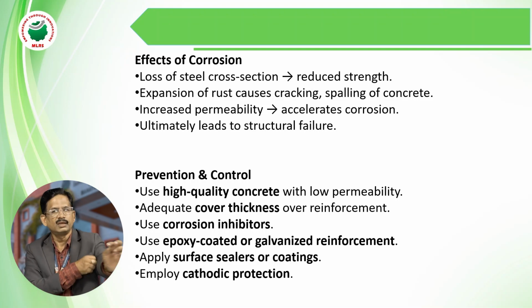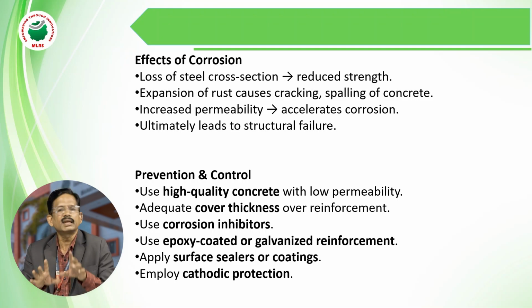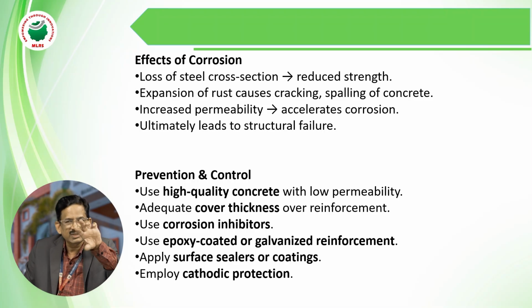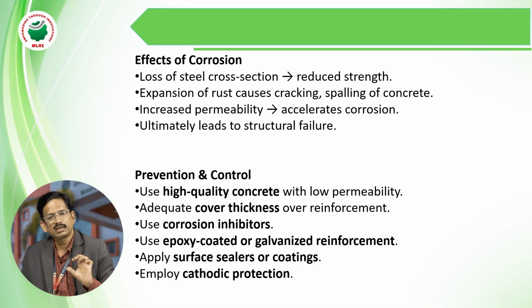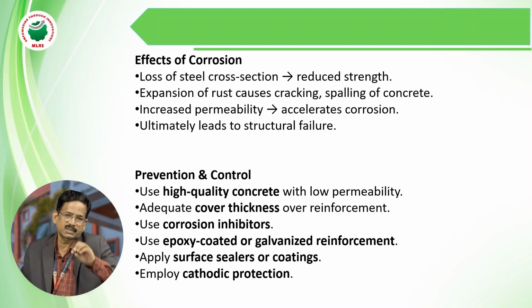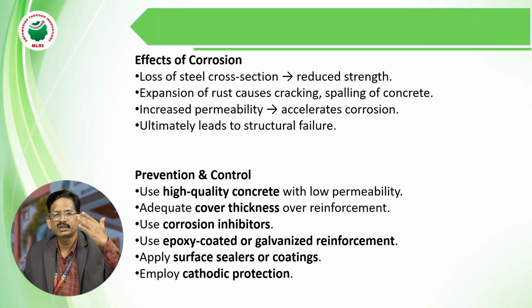So my dear students, I will tell one point clearly about that. It is interlocking. Why? Because it is the combination of concrete and steel. The corrosion of the steel reinforcement affects both the concrete strength as well as the steel strength. That's why the compressive strength of the concrete is affected and the yield strength is also affected. Ultimately it leads to structural failure. My dear students, I am telling you, no structure fails in one day or at one time. It will give some sufficient warning also.